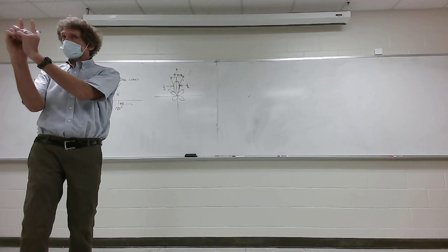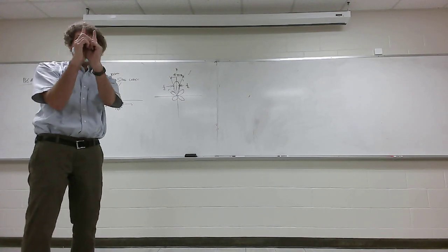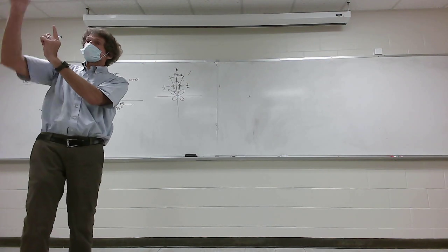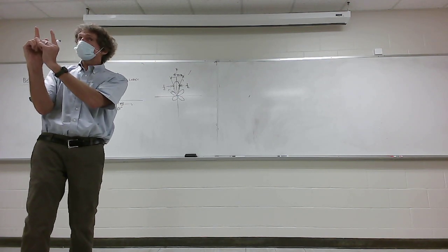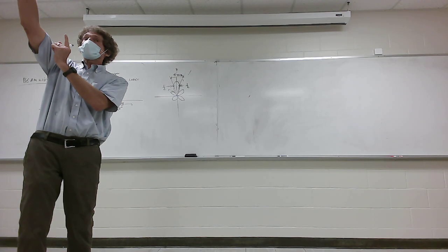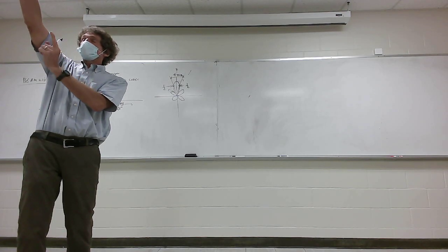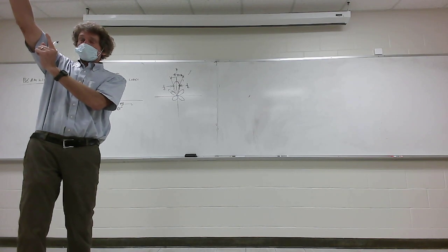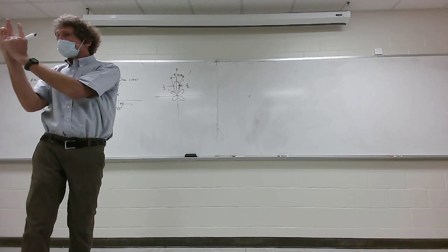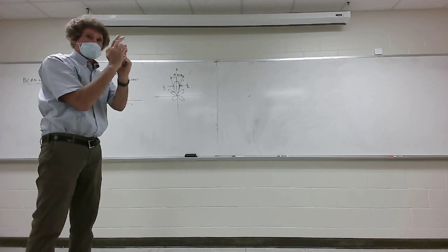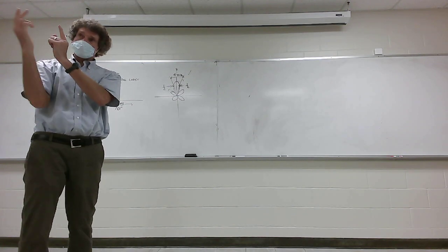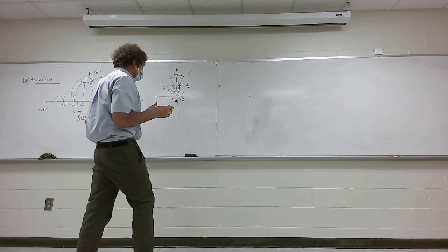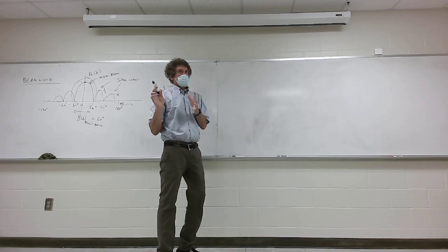They would like to have sub-degree beam widths as they scan around the surface. They don't care about the vertical beam width because if you're navigating on a sea, you don't care if there's a plane at 30,000 feet. Y'all follow me? Those are called 3D radars. You just want a very narrow beam width along the surface of the sea. These are just things to consider, and we don't go into this too far. So that's beam width in a nutshell.